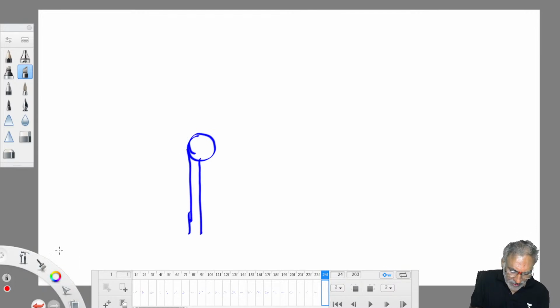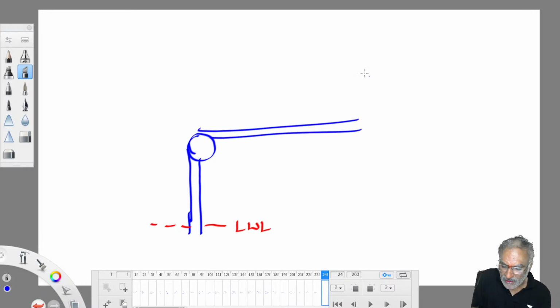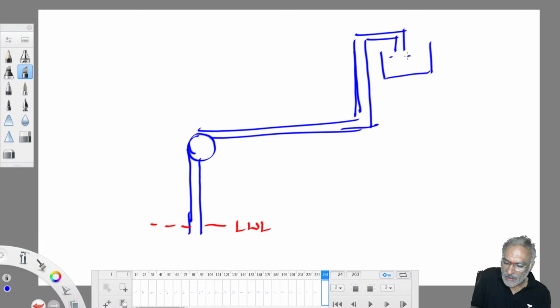We have to convey, worst case, from the lowest water level. Beyond this, no water drops down. And we take this water and deliver it to the highest point, that is the reservoir. This is the most critical situation. Here we store water in a reservoir. Lowest level to highest level we take. So what capacity of pump is required? So this is called static head.